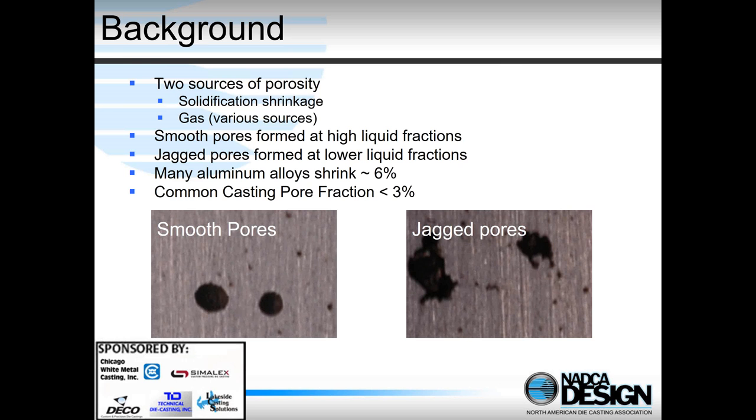As we go from liquid to solid, there's a volumetric contraction. And unfortunately, as you solidify a casting, you solidify the surface of the casting first, so that rigidly sets the dimensions of the outside. And so we don't just get a shrinkage in each dimension. What happens is generally we get porosity, or pores, shrinkage porosity it's called, in the center of our castings.